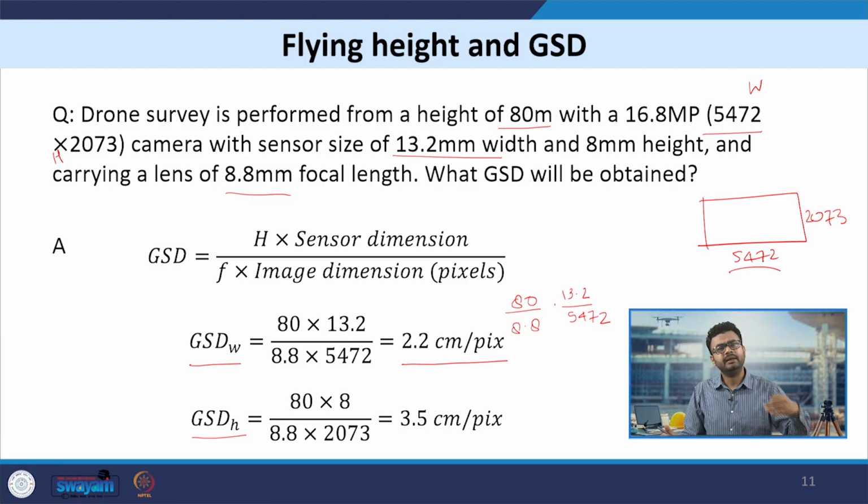So, moving ahead, next let's understand the setup for acquiring overlapping images. Why do we need them? Using overlapping images, we can estimate heights of objects which can then be used to generate a stereo model or a digital elevation model using the drone images. And we are able to estimate heights or depths of objects because any object when seen in images acquired from two different camera stations will appear to have shifted with respect to image center. In this image the object may appear somewhere here, in this it will appear somewhere here. This apparent shift is known as parallax, and the parallax allows us to measure height or depth of objects.